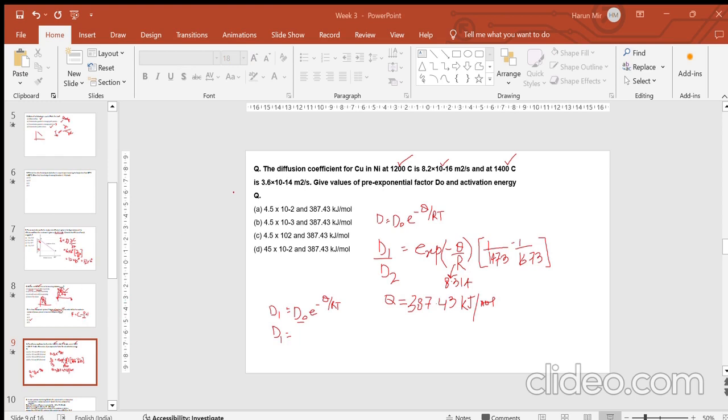Okay. So you are given, for carbon diffusion in austenite, D naught. So you are given the diffusion coefficient D naught and the activation energy Q. Okay. So you have to calculate the depth from the surface of the specimen, because this is your surface of the specimen, at which composition you have 0.4.